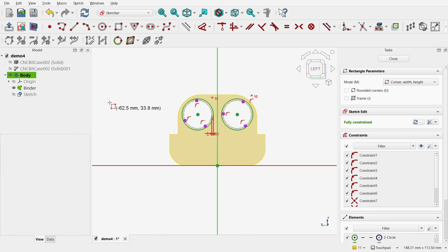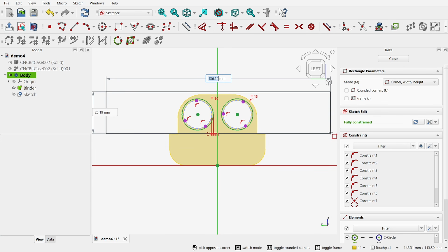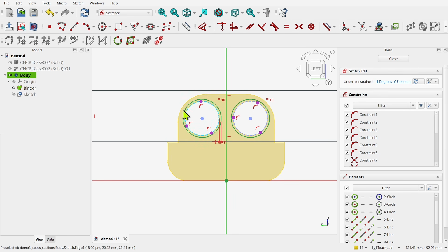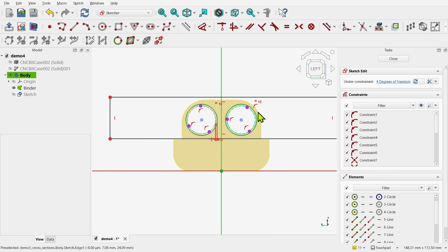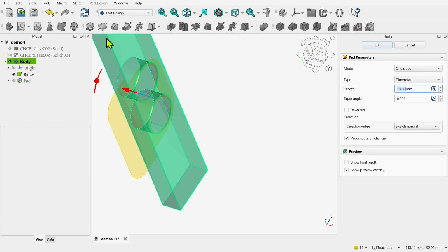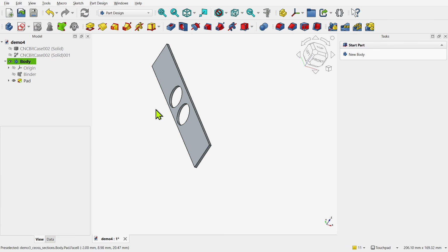And this could be part of some kind of rail that sits in here like so. And I'll just constrain this down. Wanted to make some extra holes in here because now I've got the right size of these holes. Place them in here, make them equals to each other, and now we have our interface which our model attaches to.